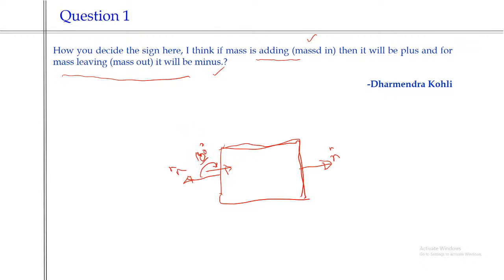That means it is at 180 degrees with the velocity. If I do the V dot n product, I'm talking mathematically, I'll come back to V dot n products, I get V cos theta. This theta is 180 degrees, so I will get minus V. But in the case of the outlet, theta is equal to 0, so you will have cos theta equal to 1. That way, when you consider the control volume, you look at the surface integral of V dot n.